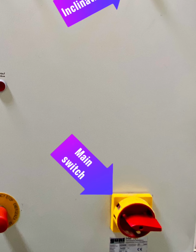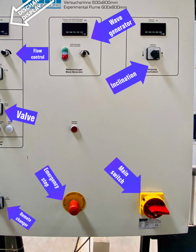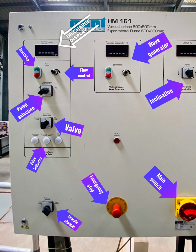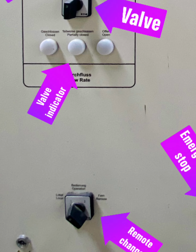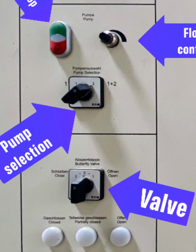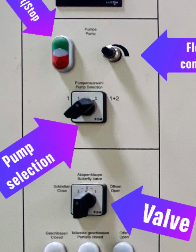This is the control panel for operating the flume. So this is the main switch. We need to turn on the main switch first before starting anything, and this is the emergency stop, and for operating either from the control or from the remote we use this button, and for opening and closing the valve we use this, and we have the indicator also, whether it's open, partially closed or closed will be shown here, and we have an option for selecting one pump or two pumps, and we can do it from the pump selection option.